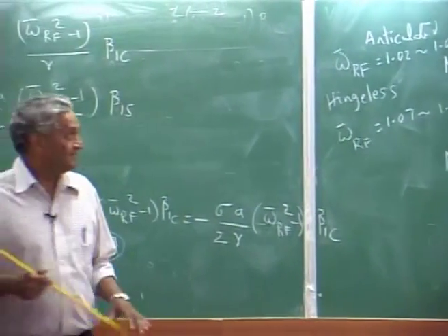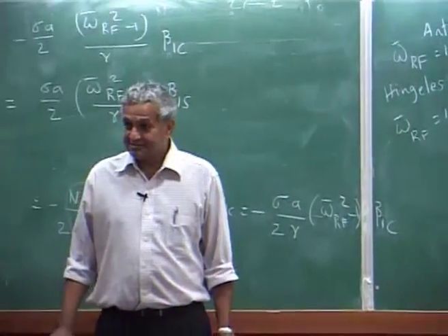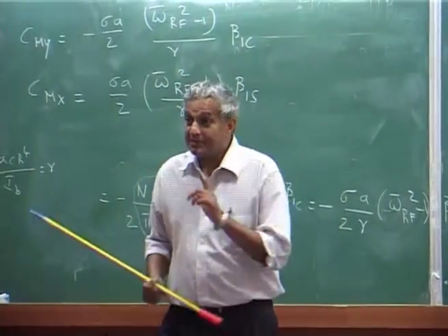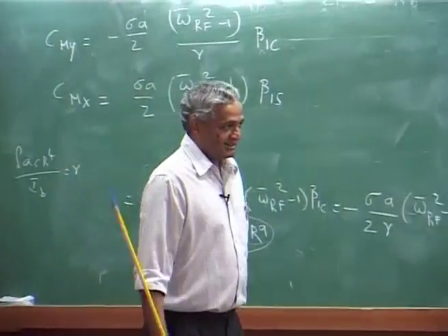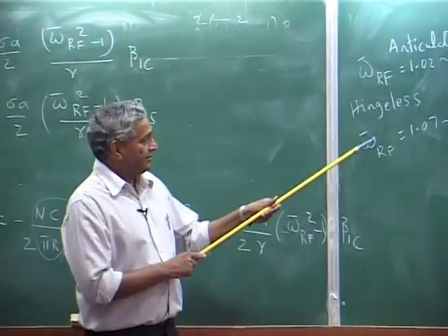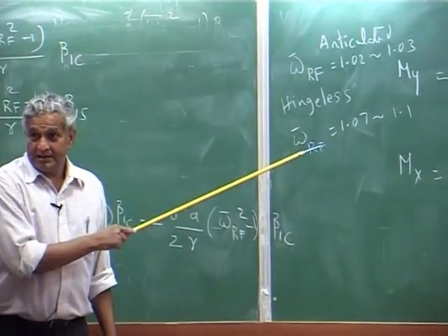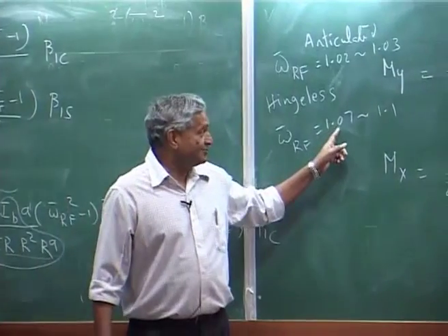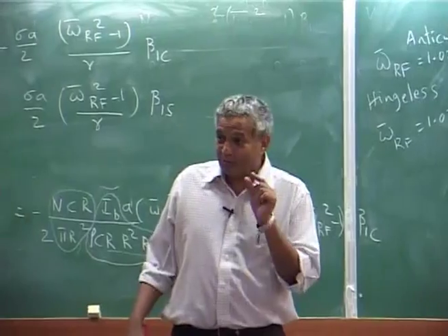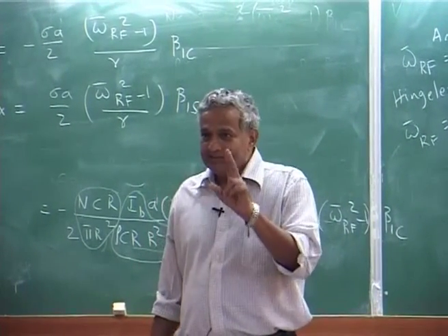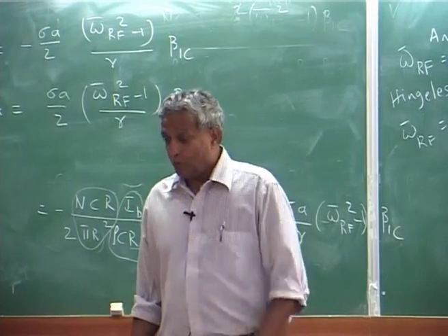Now you see, articulated rotor, because you have a hinge, but you do not have a spring. So the model is a little different; that part you will learn when we do the next section. You see the flap frequency difference, this is a high flap frequency. That is why I have written up to 2 decimal points. Industry will calculate, you will be surprised, they will want to go to at least 2 to 3 decimals in flap frequency. Why?